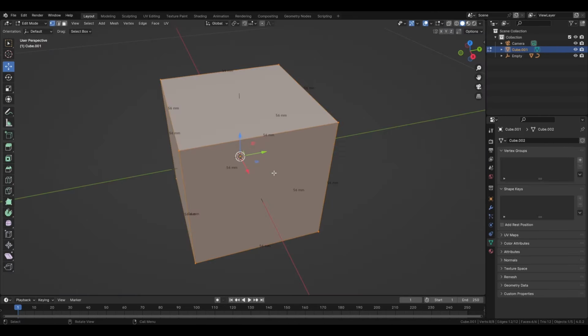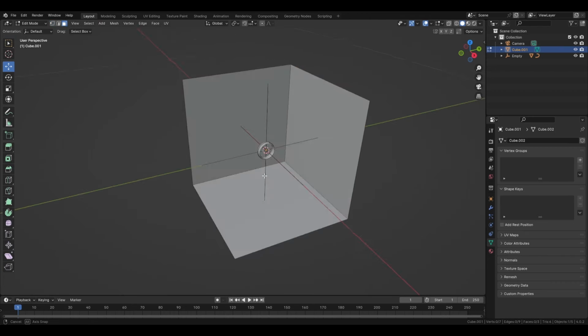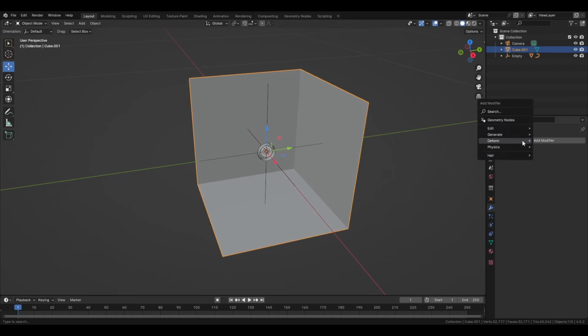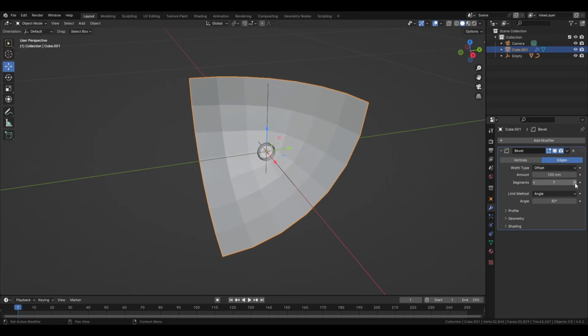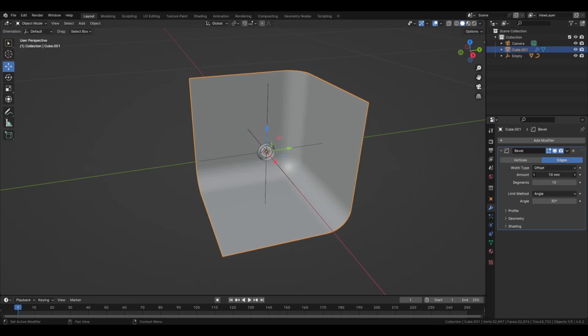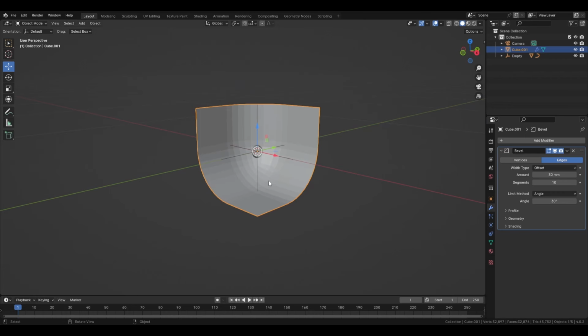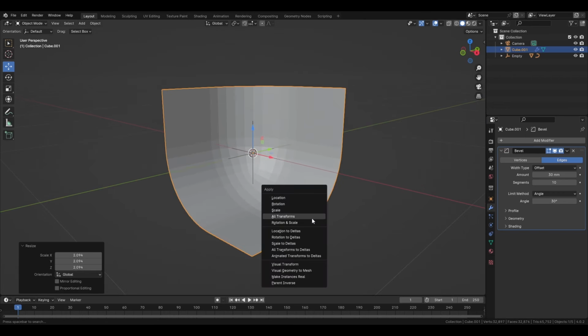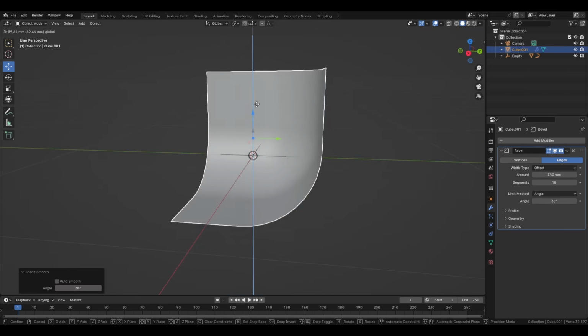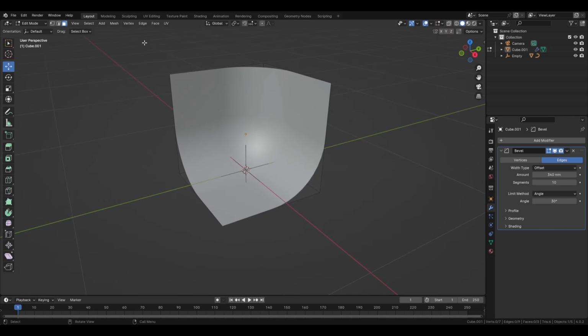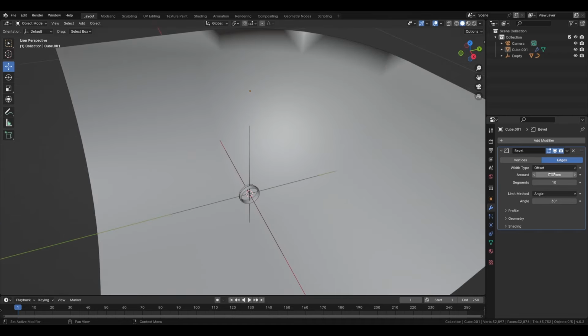So make it slightly bigger, go in edit mode, delete 3 faces here, and then add the modifier, generate bevel, and you can put this higher, and you can put this at the maximum, or actually, yeah, let's put it like this here, and let's add this slightly bigger, apply the scale, so Control A, all transform, so maybe you put this bigger, add the shade smooth here, and then you put this upper, actually take those edge here and lower it. If you have this kind of thing, you can lower this.